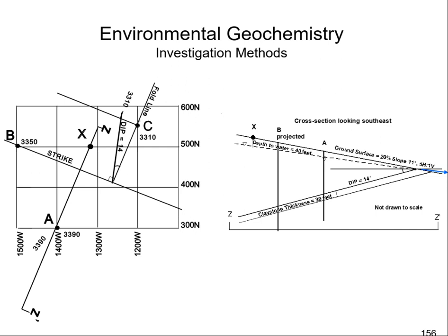One, do you understand this is an LNAPL or a DNAPL? And the other one is, do you understand groundwater flow? If we are thinking about this just being a DNAPL, it'd go straight down until it hit the claystone, and then it would turn and move down the slope through the force of gravity because it's denser. If we incorporate the principles of groundwater flow, then it's still going to be vertical through the vadose zone here, the part above the water table.